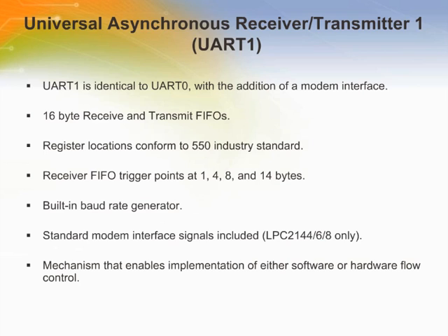This interface is responsible for handshaking between a modem peripheral and the UART1. The interrupt interface contains registers U1IER and U1IIR. The interrupt interface receives several one-clock wide enables from the U1TX and U1RX blocks. Status information from the U1TX and U1RX is stored in the U1LSR. Control information for the U1TX and U1RX is stored in the U1LCR.